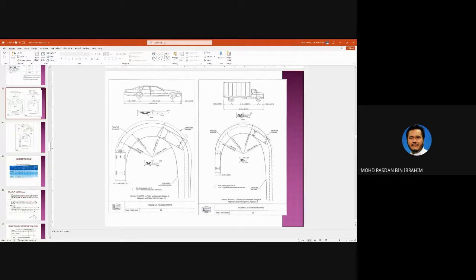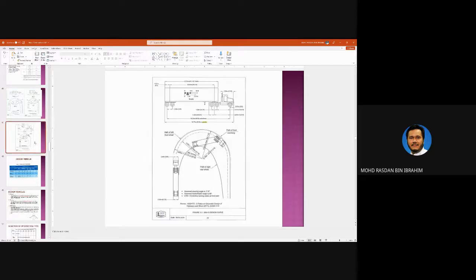The same case with SU over here. You can see the center line here is 11.5 and the actual path of overhang is 13.21. This is the most important vehicle because normally we will try to satisfy the need for WB. This is WB15, this is wrong. This is WB50 because the length here is 50 feet wheelbase. This is a typo.